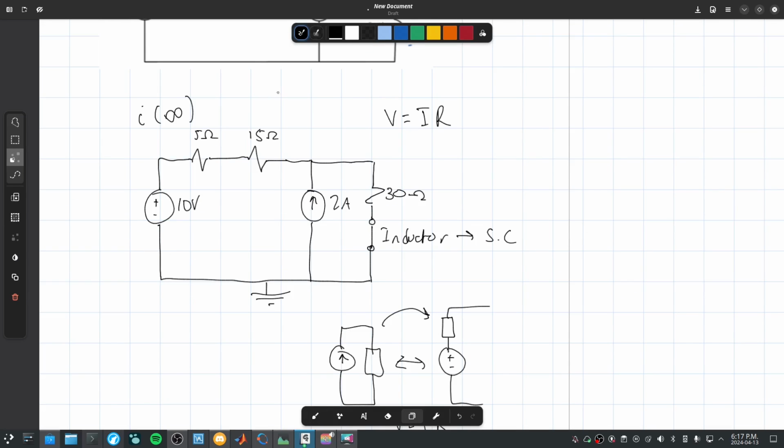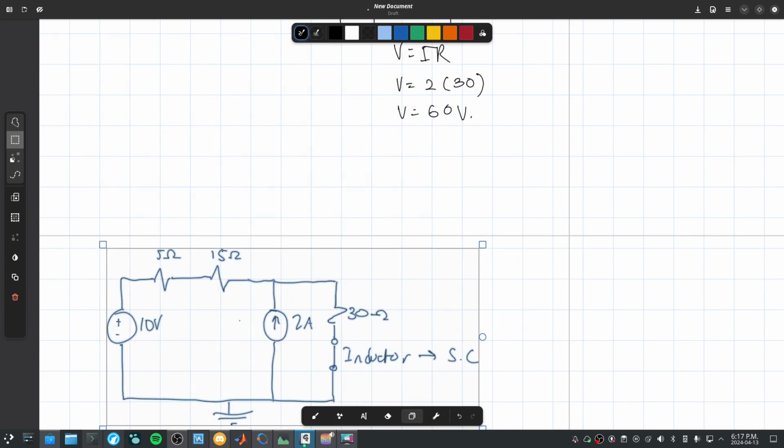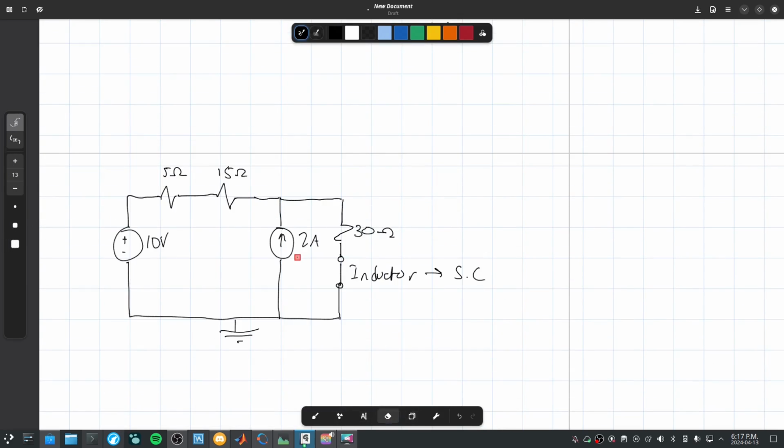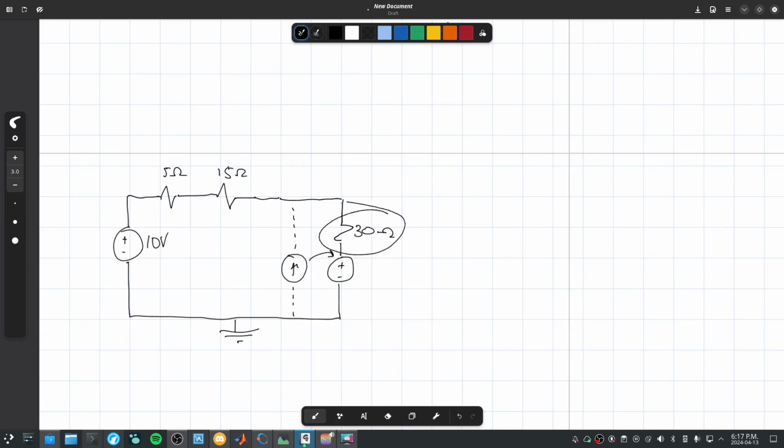So let's go and transform this circuit. Let's take this, copy it, take it down here. So now it becomes in series. And the rule is that the positive end is in the same direction as the current was. And the load goes after the positive end. So this is how it becomes after we've done our source transformation.